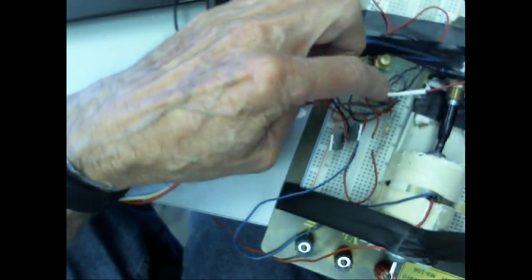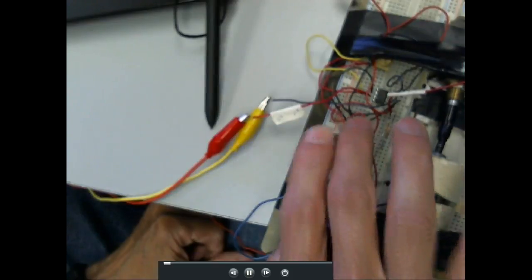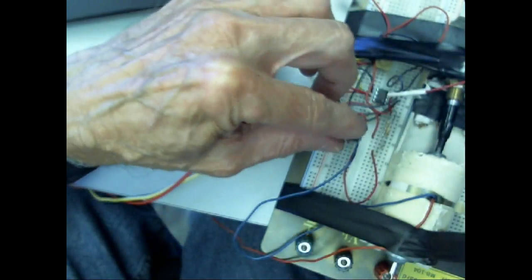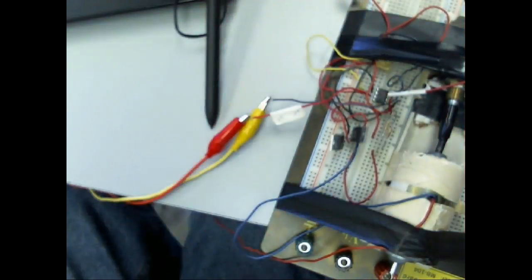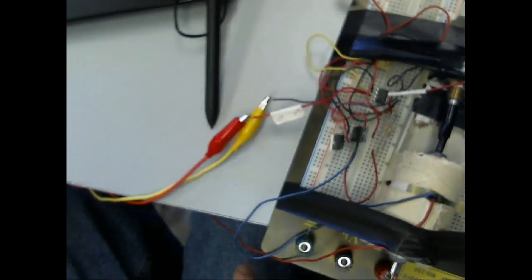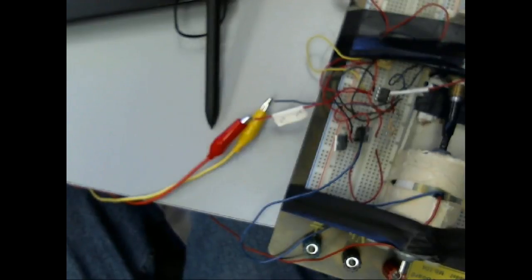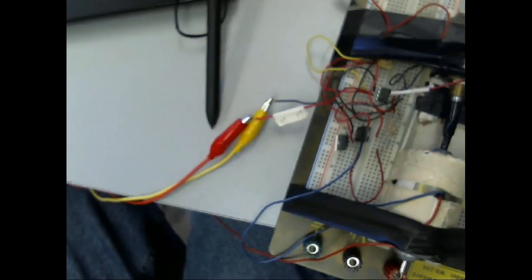And here's the error amplifier. Here's my two transistors right here. They get kind of warm. But these are the two transistors right here. I didn't draw the resistor. But one of them's an NPN, one of them's a PNP. The NPN controls the positive, and the PNP controls the negative. On leads, on a sinking and a sourcing sensor is the way they hook it. So an NPN transistor is a sinking transistor, and a PNP is a sourcing. We can show you how those work. Are we okay? Ain't that neat?